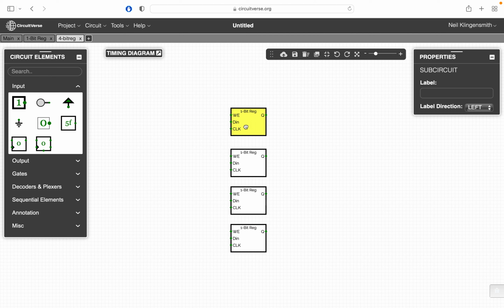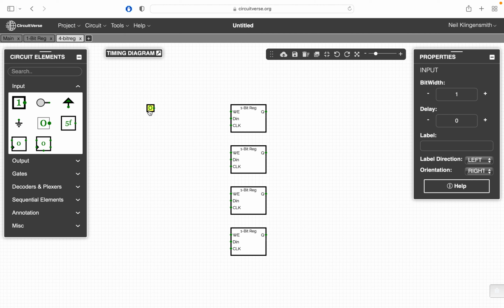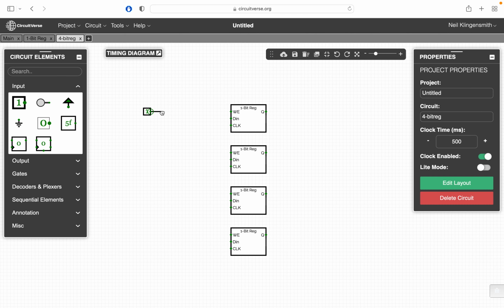And so, of course, you spend a lot of time going through a rat's nest of wires trying to find a problem like that. So when you watch me route this stuff, keep that in the back of your mind: how I keep things spaced out and try to keep the wires running as orthogonally as possible. There's an overall plan about how all this is routed, as opposed to just putting things in and sorting out the details later. It's definitely worth spending a few minutes acquainting yourself with the user interface, to get comfortable enough to route things cleanly, so that you don't waste a ton of time after your design is finished and there's some kind of problem that you can't find.